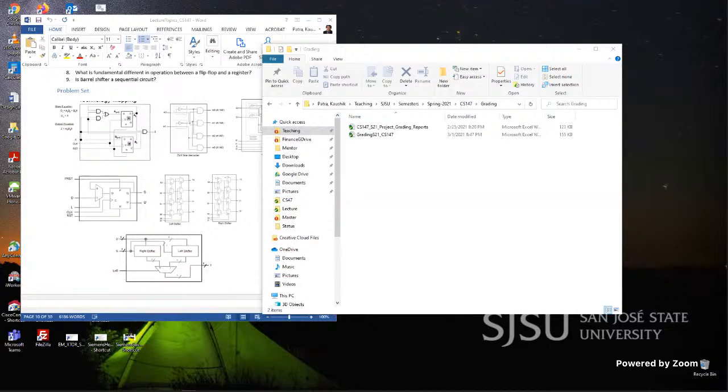That means I can shift between 0 to 3 bits, 0 to 3 in decimal value. Shift by 0 bits means no shift, shift by 1 bit, shift by 2 bits, shift by 3 bits. Anything more than a shift by 3 bits will result in 0. We'll handle it separately. But let's say our range of number of shifts is from 0 to 3, which is represented by 2 bits. So this is my shift amount, 2 bits. This is my input, 4 bits, and this is my output, 4 bits.